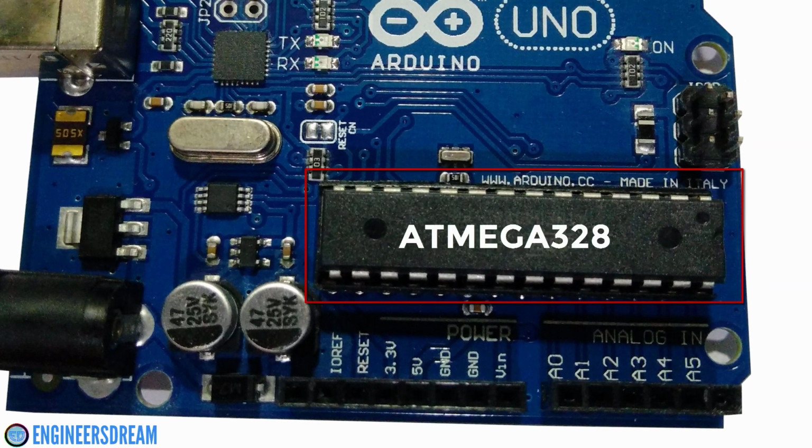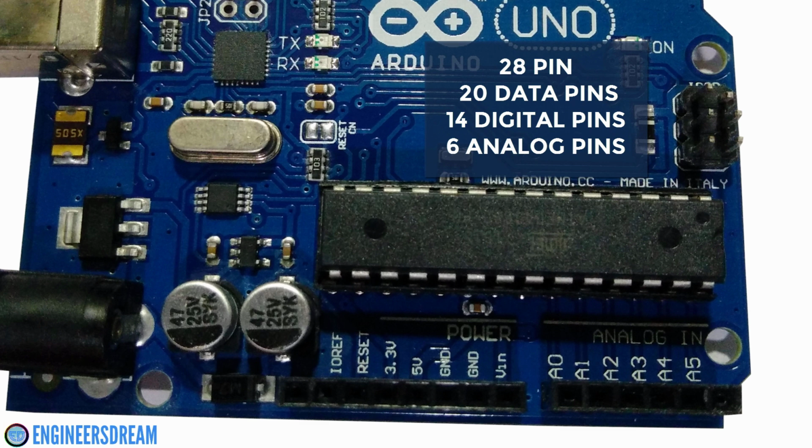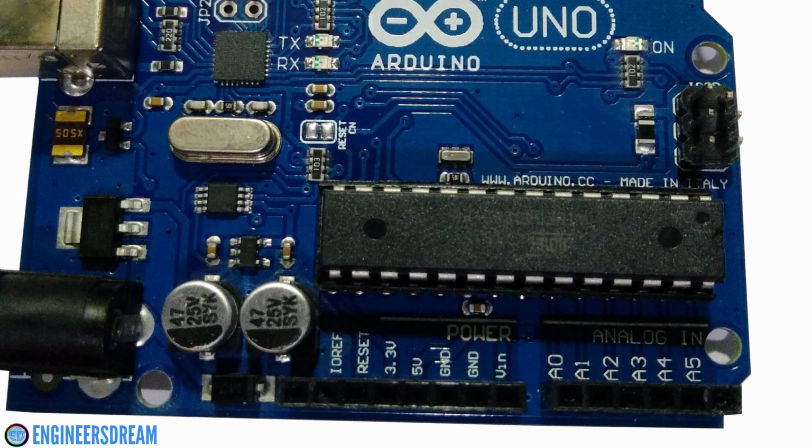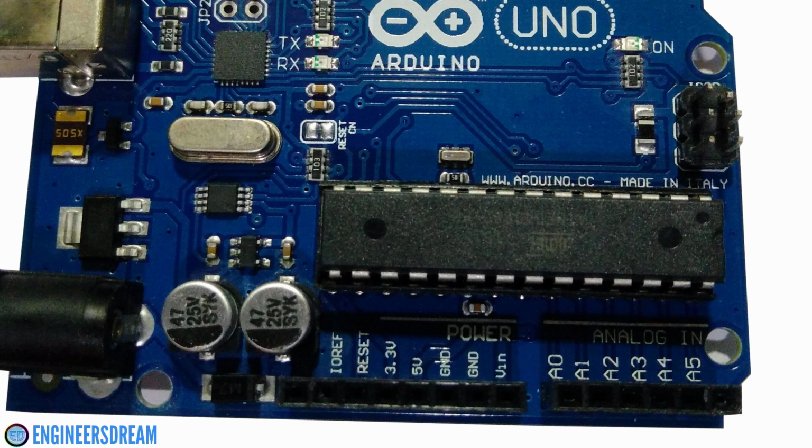Next, let's talk about the Arduino microcontroller board. The Arduino Uno consists of an Atmega 328 microcontroller. The Atmega 328 is a 28-pin microcontroller, out of which 20 pins are data pins. Out of these 20 data pins, 14 pins are digital data pins and 6 pins are analog data pins. We can use the data pins either as input or as output. Some technical specifications of this microcontroller are: it consists of a flash memory of 32 KB, SRAM of 2 KB, EEPROM of 1 KB. The Arduino board also consists of a 16 MHz crystal oscillator.